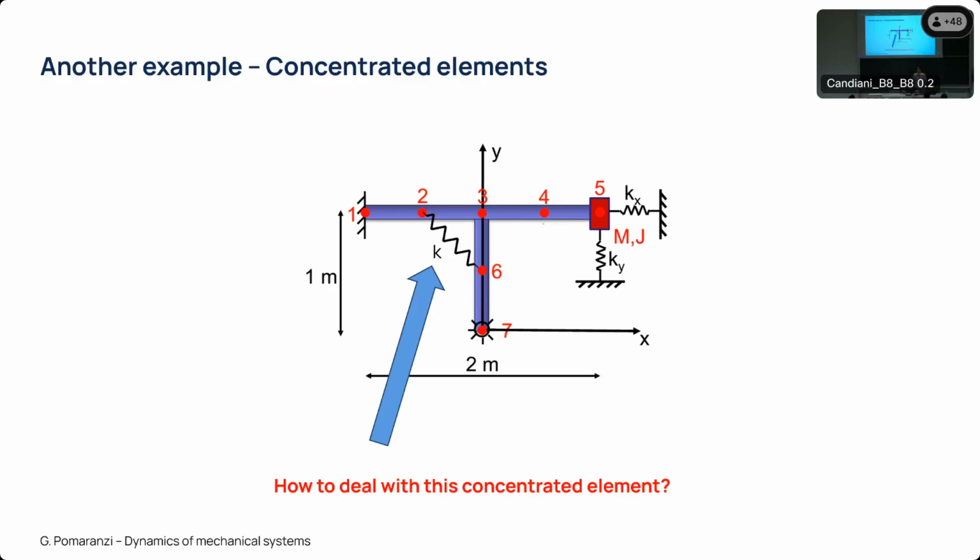In this case, we have to create a workaround based on the fact that if there is a relative displacement between node 2 and node 5, that will affect the global stiffness of our structure. So we won't have only contributions on the diagonal, but we will also have 2 extra diagonal terms corresponding to the relative displacement of node 2 with respect to node 6, and vice versa.